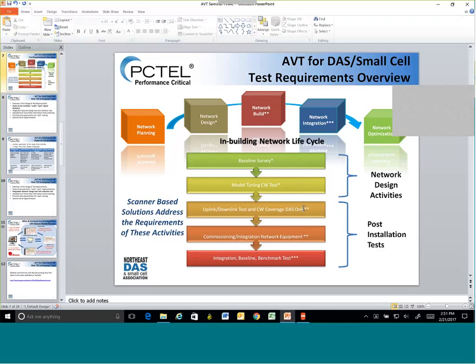You put a CW transmitter in the head end, you walk out under each antenna, and you make sure that the right level is coming out based on what you put in. Same kind of thing, you put transmitters out at the remote, you go up to the head end and use either the signal analyzer or the AVT with a regular scanner, do port-to-port checking, and look for noise floor, noise rise, all those types of things. So the answer is yes. It's much more efficient to do it that way.